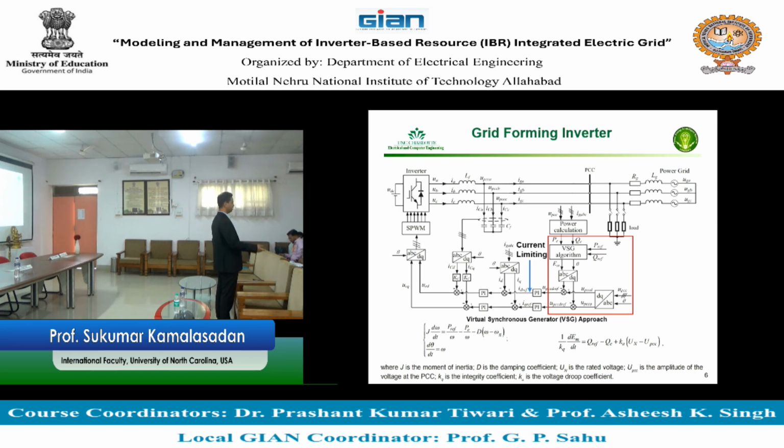Okay. So why is the swing equation second order? Because there is d delta divided by dt, or d theta divided by dt, the derivative of the angle, equal to the angular velocity omega, and the derivative of that omega, d omega divided by dt, is (Pm minus Pe) divided by 2Hs, where H represents inertia, Pm represents the mechanical power, and Pe represents the electrical power.